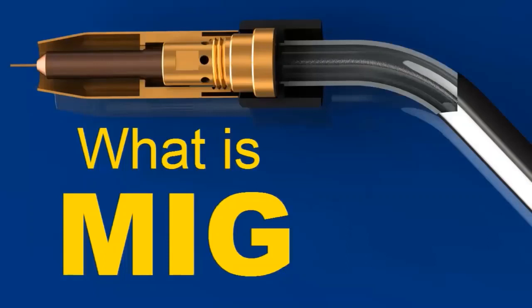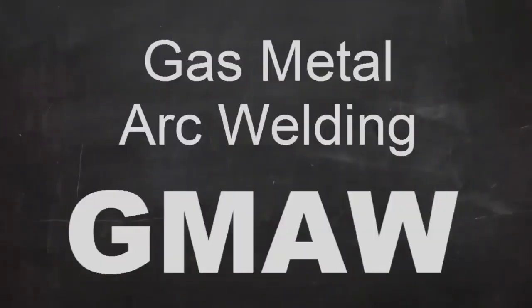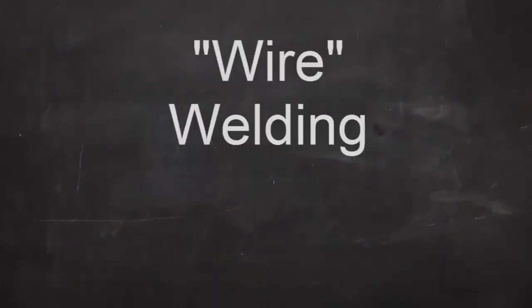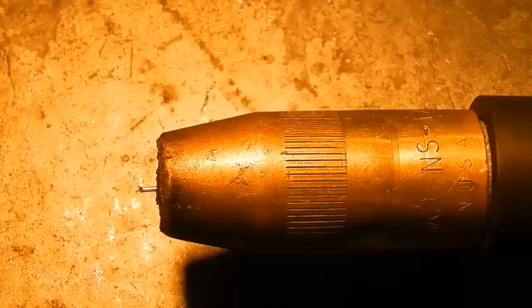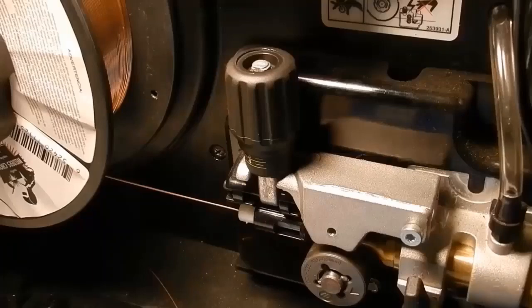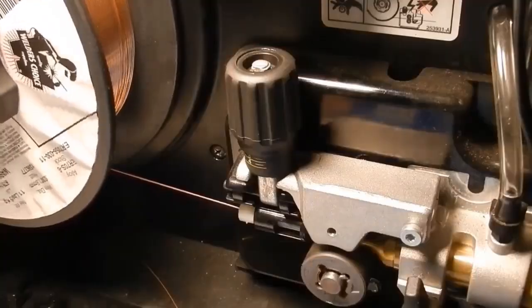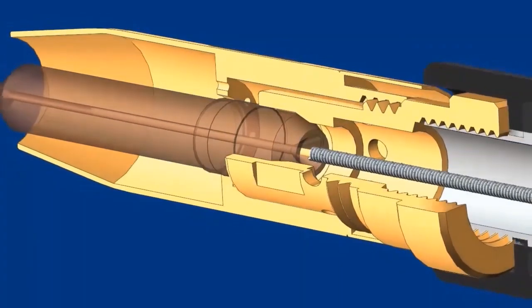What is MIG welding? MIG stands for Metal Inert Gas welding. The American Welding Society calls this process gas metal arc welding, or GMAW. You might also hear it called wire welding. In MIG welding, a thin wire acts as the electrode. This wire is fed from a spool mounted on a gun or inside the welding machine through a flexible tube and out of the nozzle on the welding gun or torch.